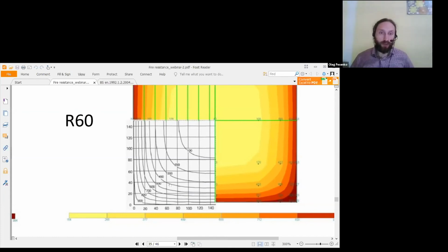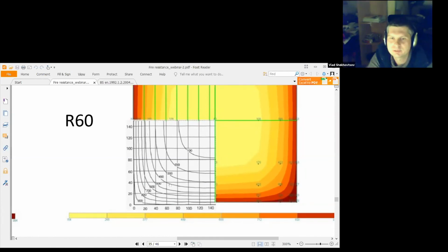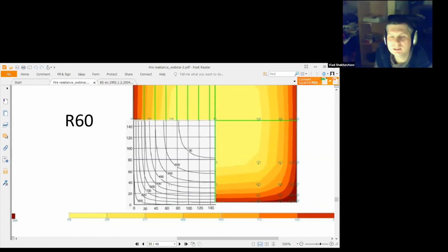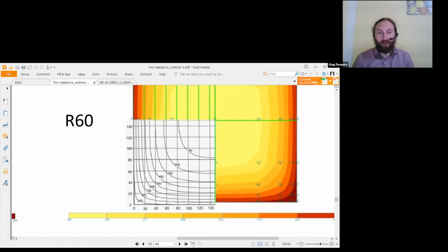After 1 hour of fire exposure, we can assume 500 degrees in the reinforcement situated at the axis distance of 40 millimeters. And the reinforcement could start to yield at such a temperature. If we use the 500 degrees isotherm method, we can neglect this reinforcement. We can talk about maybe zero strength, for example. Okay, understood.